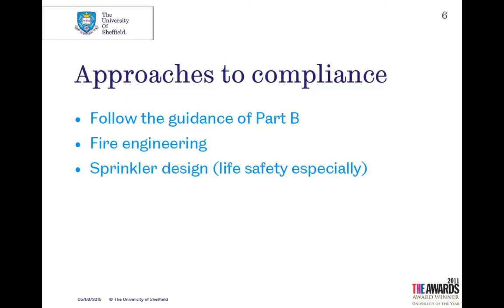Now, for you, in your design projects, what I would suggest is try and work to the Part B requirements, which I'm going to summarize here. But if you find in your project you really can't, and you don't want to redesign your building, I think it's perfectly acceptable, if you're questioned on that or in your technology report, to put in a little section that says, look, I'm aware that this escape is not Part B compliant in terms of the guidance, and so we would have to adopt a fire engineering route here.